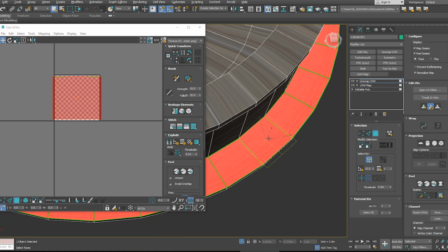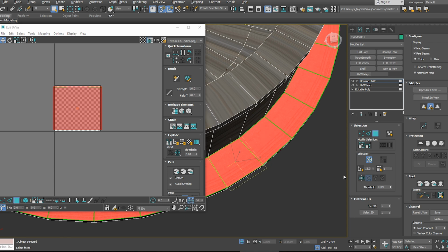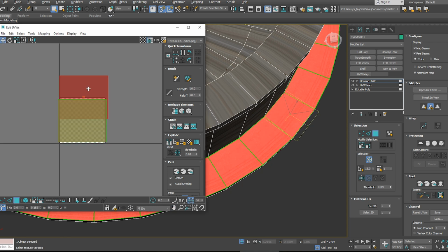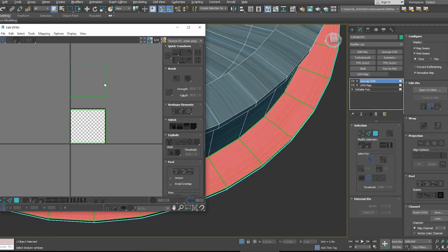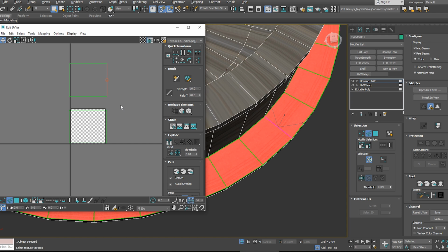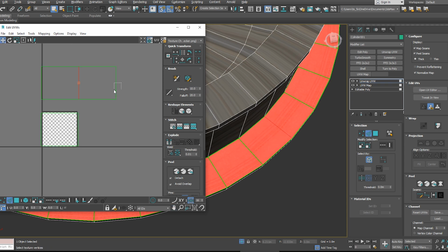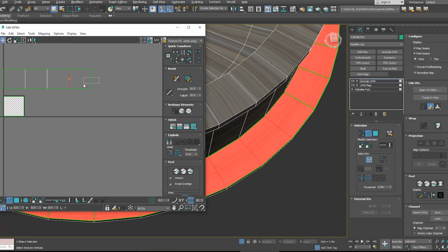So when I grab this face, I usually just select on my mesh, any one, it doesn't really matter. Move it above it, because they're all stacked on top of each other. If you start stitching, it's going to maybe be a bit confusing. So I just move it up here and start stitching my strip together. So go into edge mode, and then just Shift S, the hotkey I have set up, and I just quickly stitch out the entire strip.